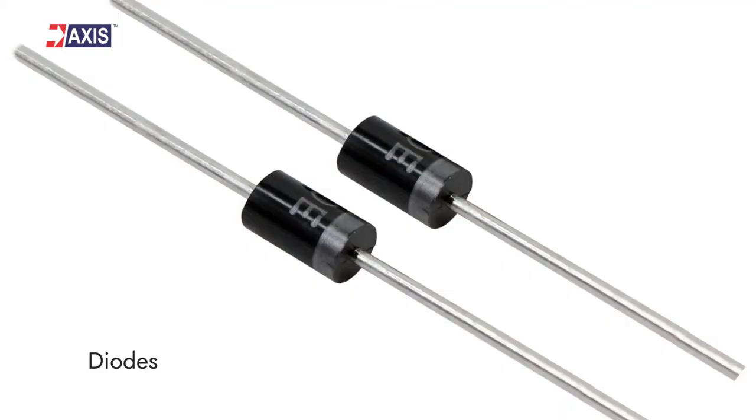Type 3 SPDs, also known as Class D SPDs, are recommended in LPZ3 areas. These SPDs have a low energy handling capacity and are installed at the end points of the electrical system, such as your socket, so that they can respond quickly during a surge. Materials like diodes are used in the construction of these SPDs, allowing them to manage surges safely.